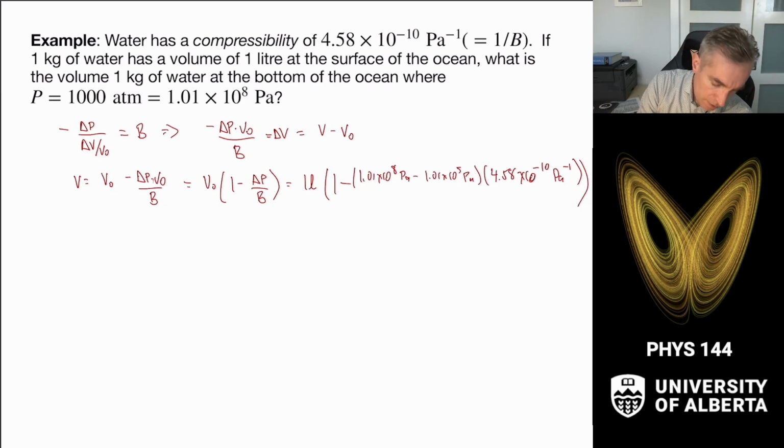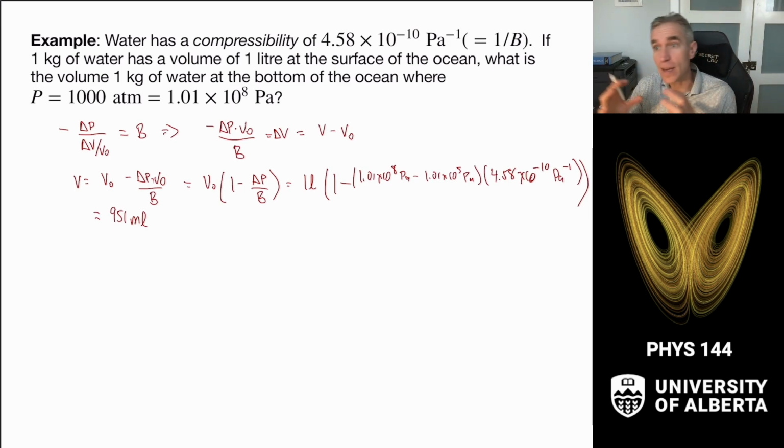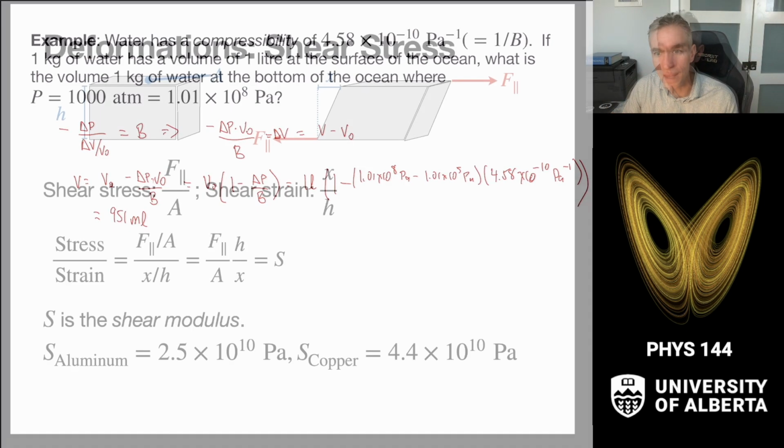And if I plug in all of my numbers, I come out with this answer being 951 milliliters. And so we crunch down, we get about a 5% change in the volume of water here. So water is actually pretty incompressible. It holds itself up pretty well as we get here.